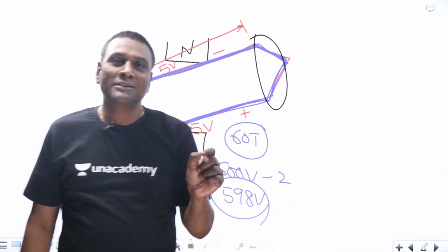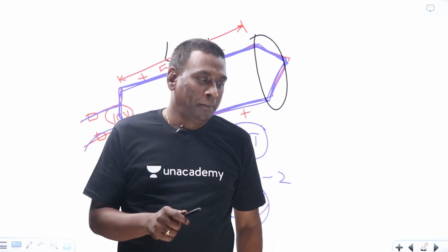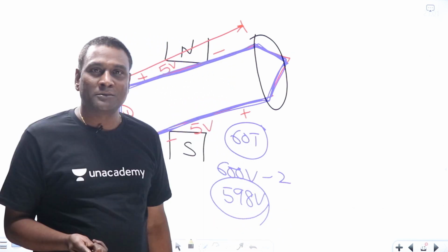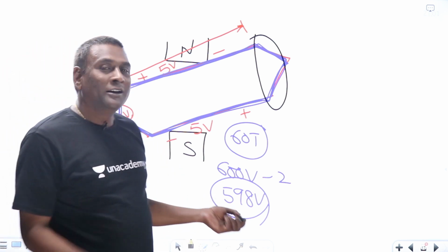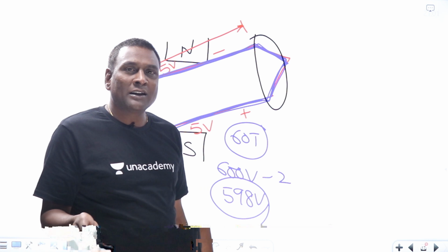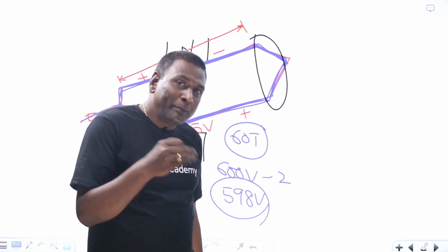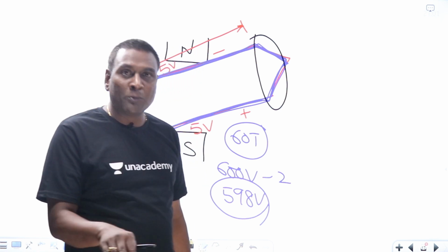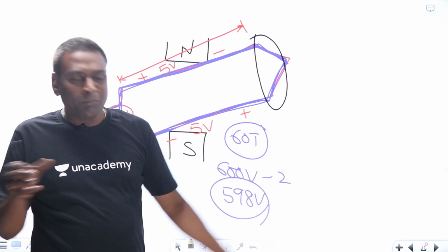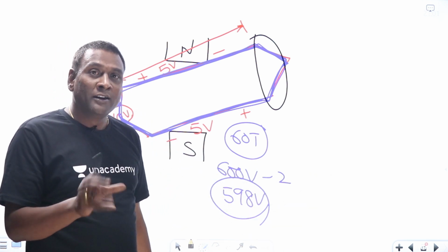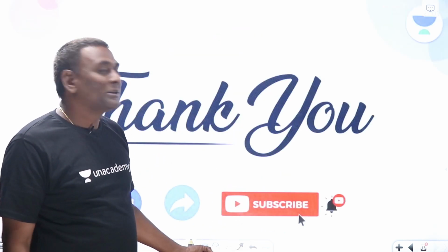The back-to-back connection decided that all commercial machines should be of heteropolar structure. Otherwise, you would maybe have got homopolar also. In homopolar, because of the lack of back-to-back connection, a significant amount of voltage cannot be achieved. Even without the back-to-back connection, if you want to achieve a significant amount of voltage, the length of the shaft should be so high, the number of brush rigs should be so high, the number of slip rings should be so high. That's the thing. So commercially, it's not possible.